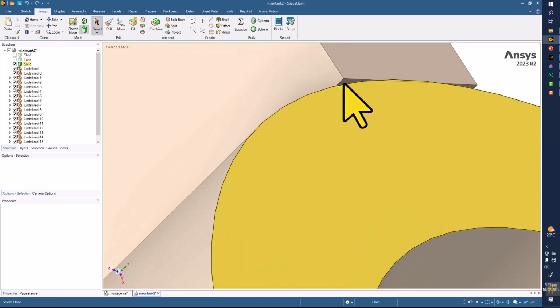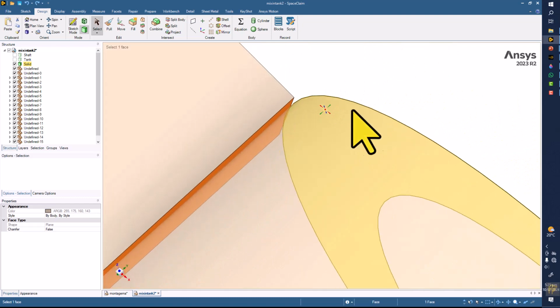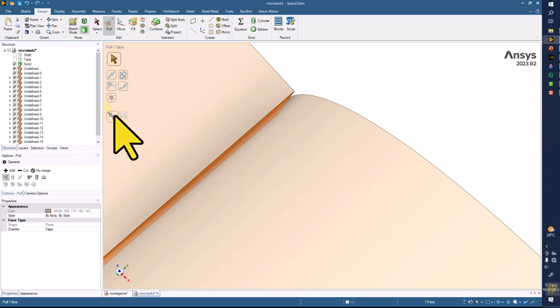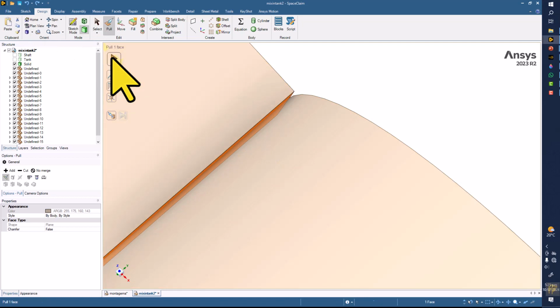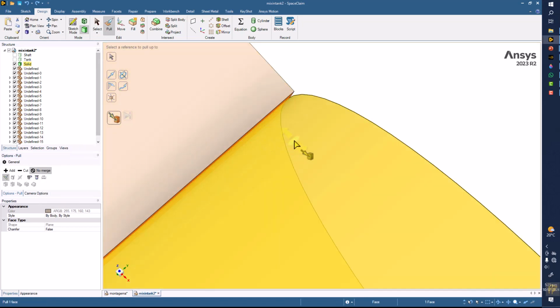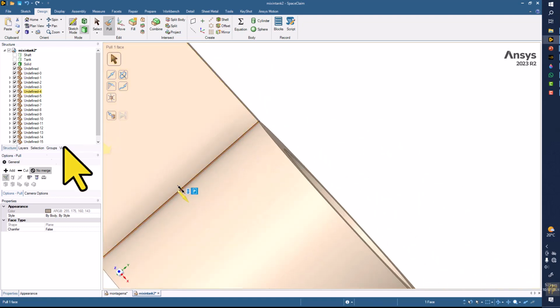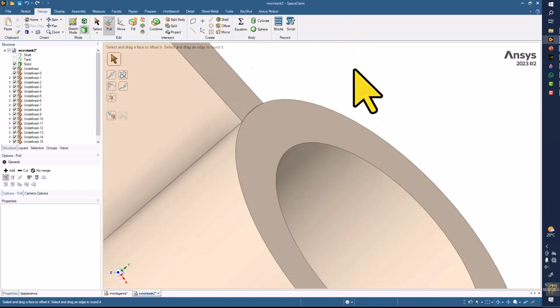So once again, we have to extrude this geometry up to this surface. Okay, so take it back and click on no merge and up to this surface. Okay, it is doing it if you use the add command, otherwise it's not making any progress. So again with the add command, and okay, this is making it correctly.